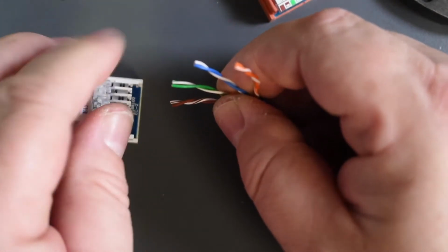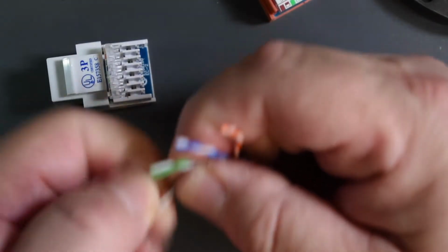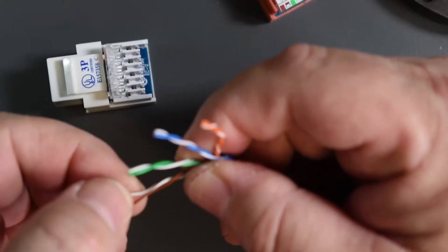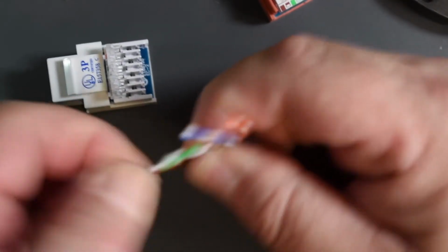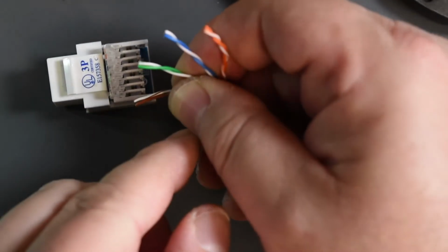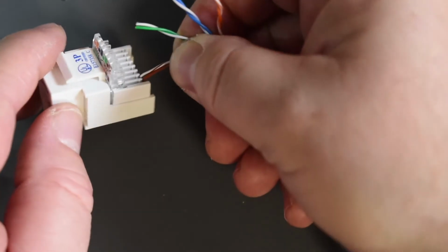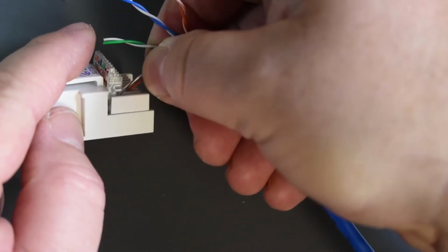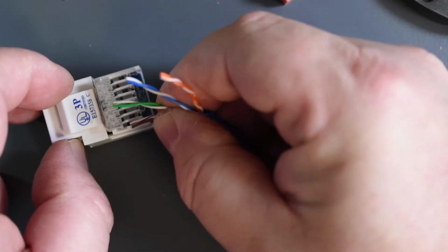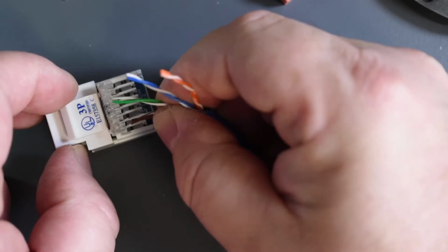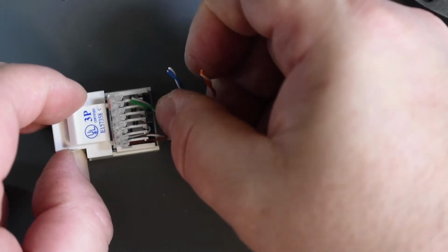Right now we can't insert that in the grooves when they are twisted like that, so we have to untwist them a little bit. So I'm just going to untwist them just enough. Then I grab them and shake them a little bit, just to get rid of the residue of the twist. And remember, I'm putting them at a 45-degree angle, just so the brown solid can go past the connector here. So once we come down with the hinge, we're going to push it in.